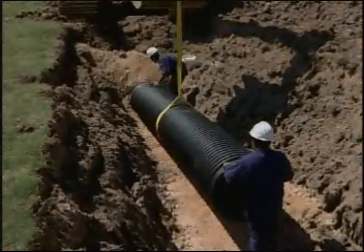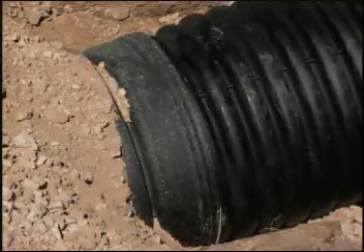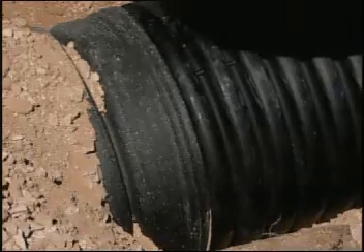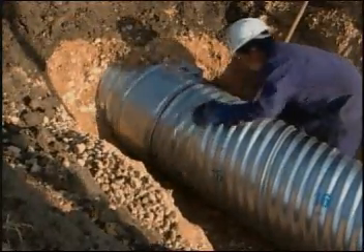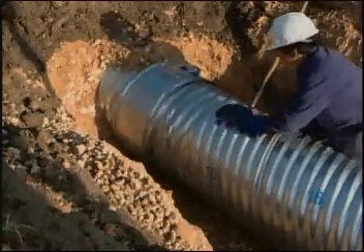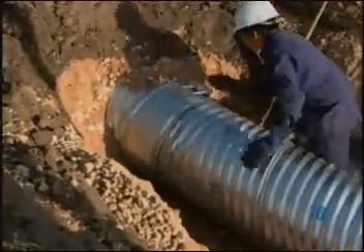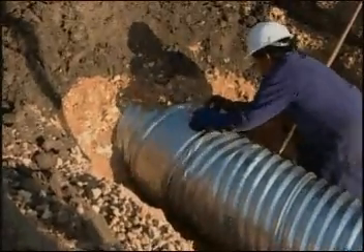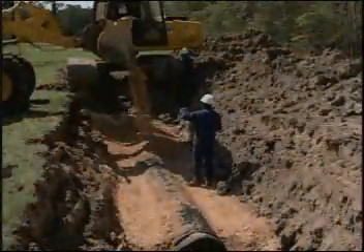Also vital, leaking joints can promote migration of fine soil from the embedment materials, a critical problem if the migration destroys the structure so important for the flexible pipe the contractor works so hard to build in the trench soil. Once the flexible pipe deflects, joints become more difficult to assemble and are less efficient.